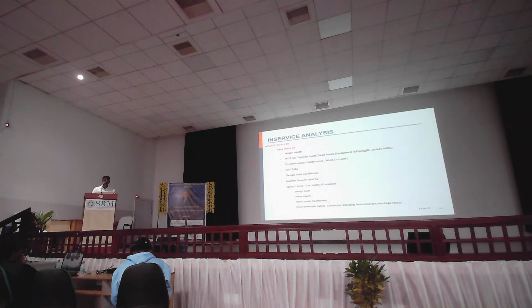And proper soil data. Even if you are going for 100-meter piling, we need a minimum borehole depth up to the 100-meter depth. And water depth, marine growth at the location, because marine growth will attract more wave forces. And what is the water condition and environmental condition there, whether it is a more corrodible zone. Then we have to choose the steel, and we may need to put higher thickness steel on the topmost wave placement area.